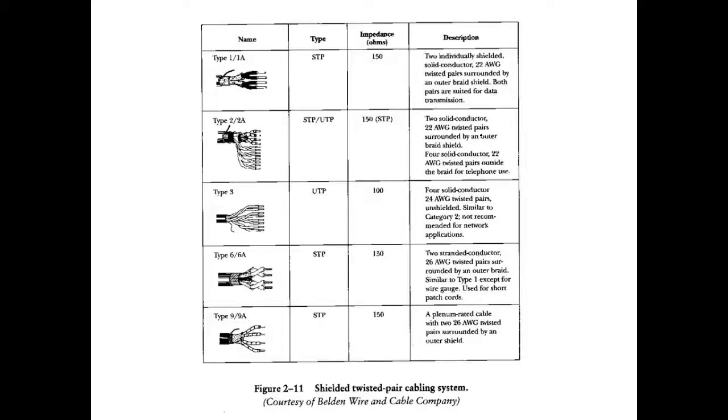This makes sense. And the UTP impedance. So here's impedance. But this impedance only becomes true if you maintain the what? The twist. Within certain limits. I think it's 1/4 inch. So we can untwist them about 1/4 inch and still maintain the impedance of the cable. Because a 1/4 inch on one connector and a 1/4 inch on another, that's 1/2 inch. So that's a 1/2 inch. But you've got to do both sides of the connector, right?